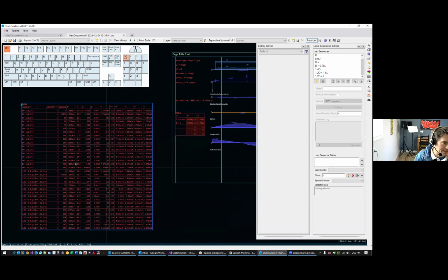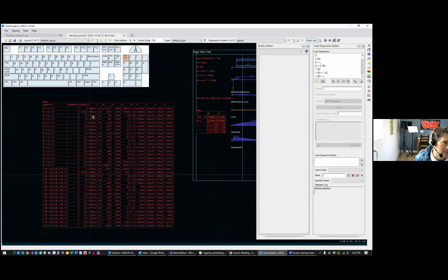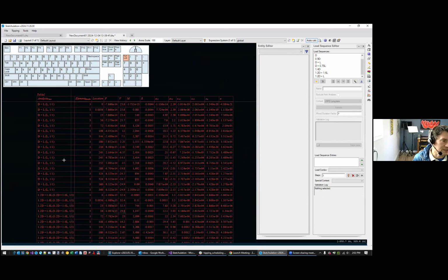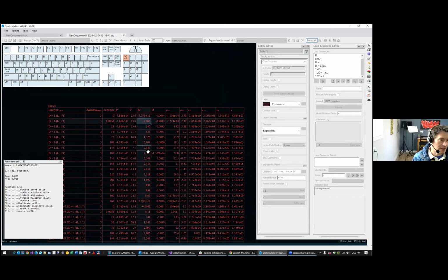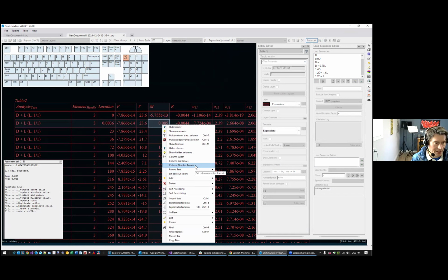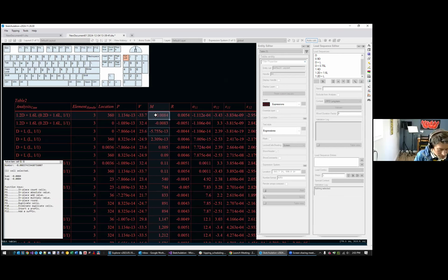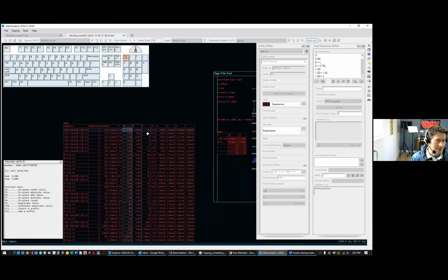Now again, this is giving you all of the responses at every location. And the extrema would condense the load case into just one row with the worst case of all these results. We can sort it here, maybe the repetition. In any table, you can select a cell and right click. I always do this by the quick keys, but Control U to sort the entire table like that. Control U, Control D, like that. Now, is that close to what you're looking for?